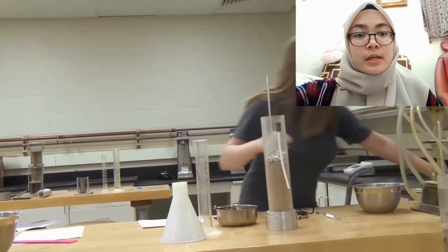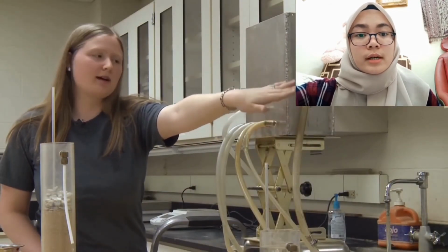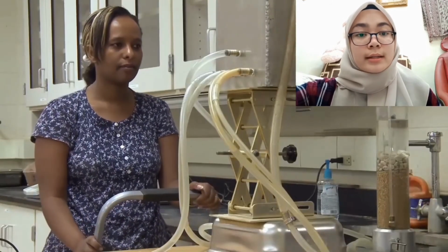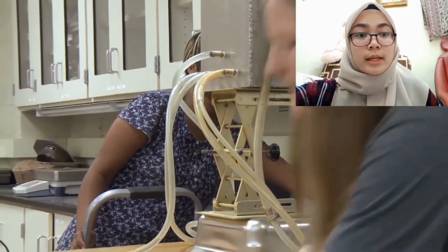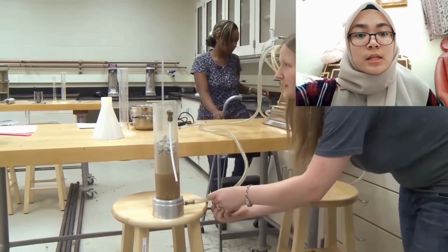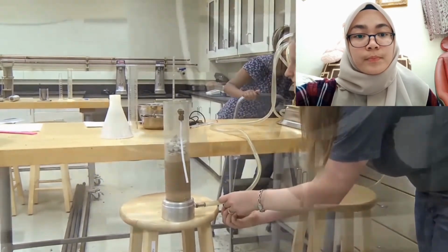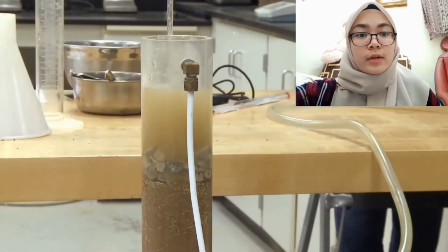Next, hook the sample up to the water. Set up the water source connected to a faucet. The faucet runs into the reservoir. Need to unclamp the hose so that water can flow into the system. Slow down the water a little bit and wait for equilibrium to be reached, and the outlet is now going into our catcher. To determine that equilibrium is reached, observe the water level in the manometer.